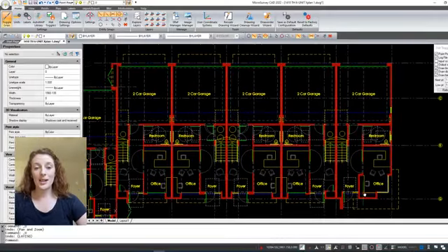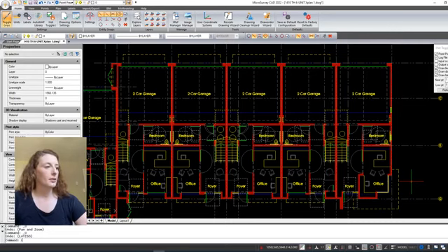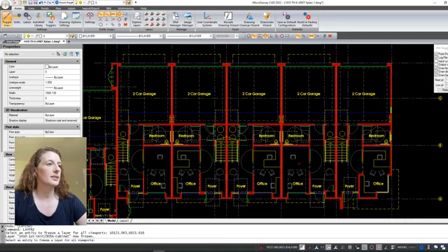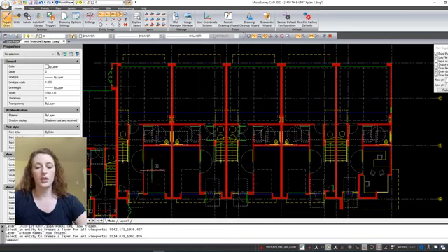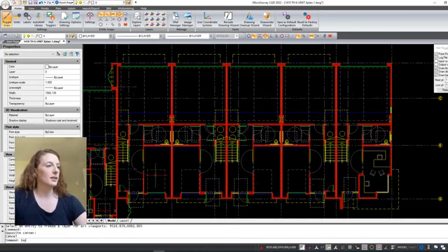Okay, so in regards to layers in a drawing, you can freeze or thaw layers, and the command to do that would be LAYFRZ for layer freeze. And this means I can go in and say, if I'm like, okay, I don't want to see the desk, I don't want to see the furniture, you can go in and pick and choose to freeze the information that you don't want to see.